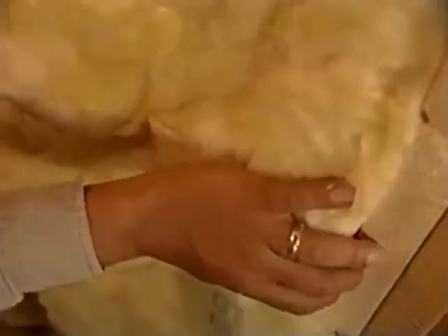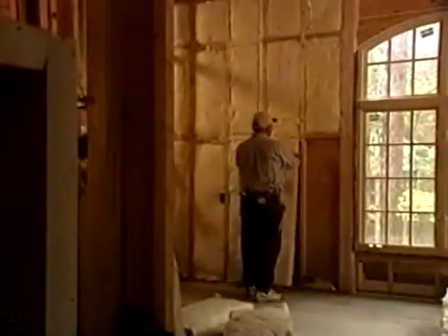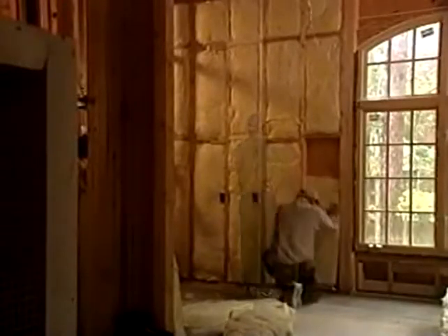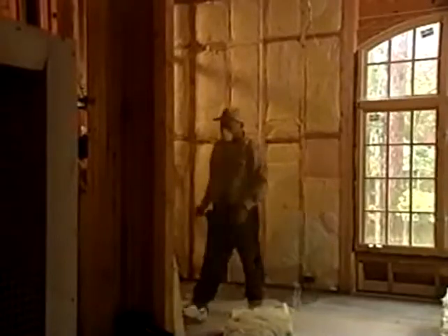When you have an electrical box in a stud cavity, it's also important to split the insulation. Take the back part and slip it behind the box. Then lay the top part of the batt on top of the box and cut around it. Careful not to leave any gaps. If you follow this procedure in walls, ceilings, and floors, you will reduce the amount of compression and allow the insulation to work at its full R value.